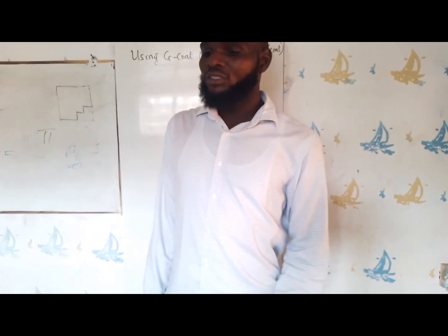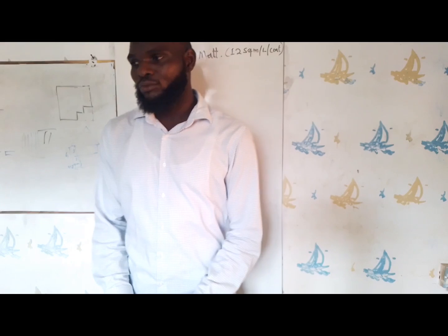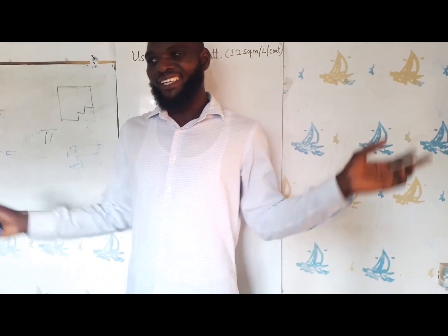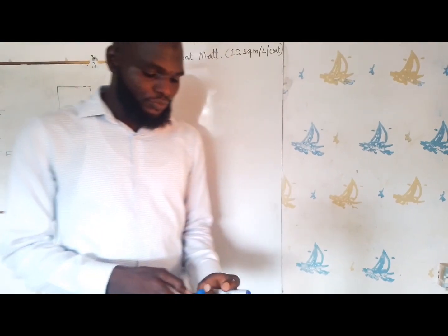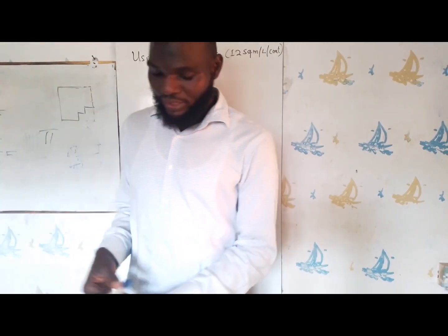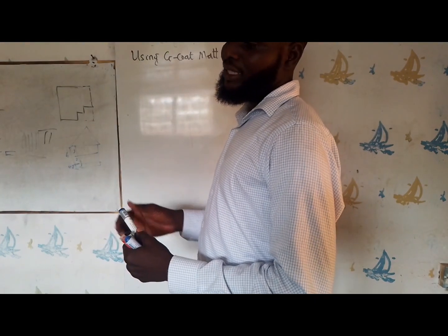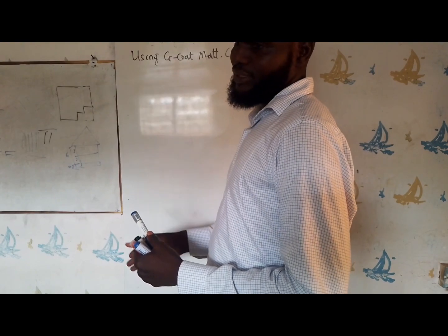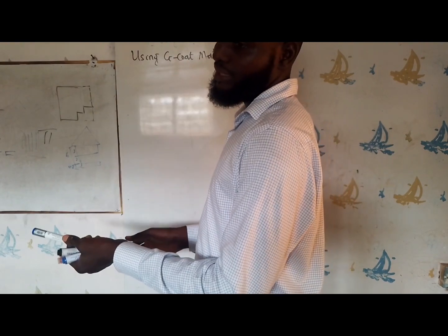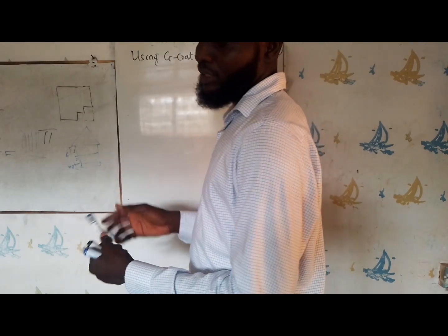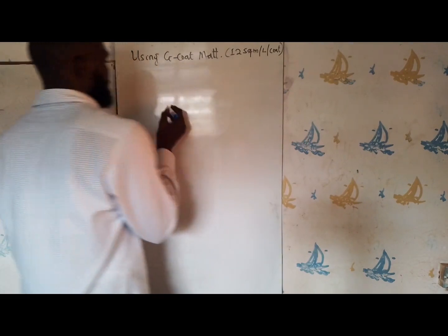So now we need to deduct the areas we are not painting, like all the openings that are external. So now let us itemize them. We need to list them. The openings on the length, on the right side of the building, the one on the left side, the front and back, their sizes.